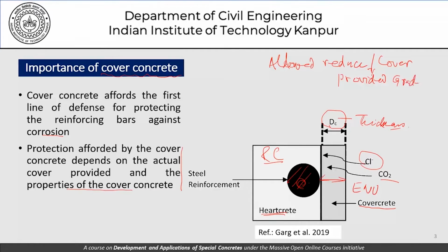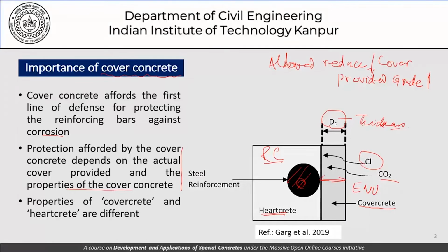So that's a good point that you should remember, that yes, the ultimate protection is what's important, and it is provided by a product or a combination of two things, the thickness and the properties. So the properties of cover concrete, called covercrete, and hardcrete are different. Now how they become different is something which we'll just quickly examine.